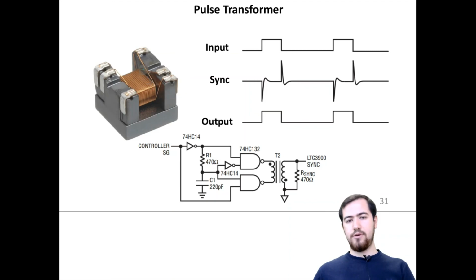This is a pulse transformer, which has a PWM signal input. When it is in the steady state, it does not cause any change on the state of the secondary side. However, whenever a dV/dt occurs on the primary side, we see an impulse on the other side, and this signal can be coupled with another IC, and this can be converted to a turn on or turn off signal with that IC as well. A pulse transformer schematic circuit is shown below.